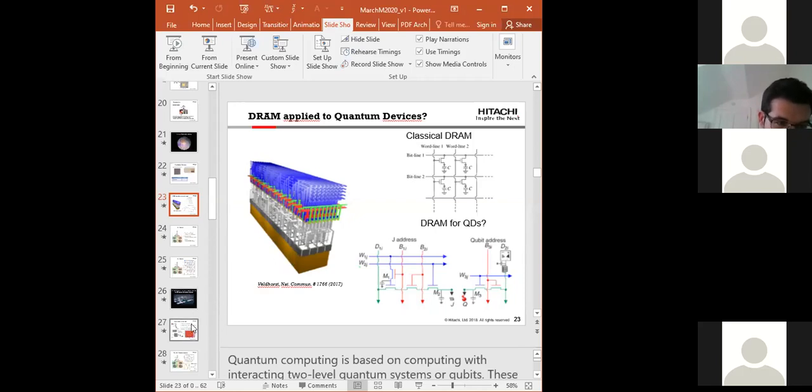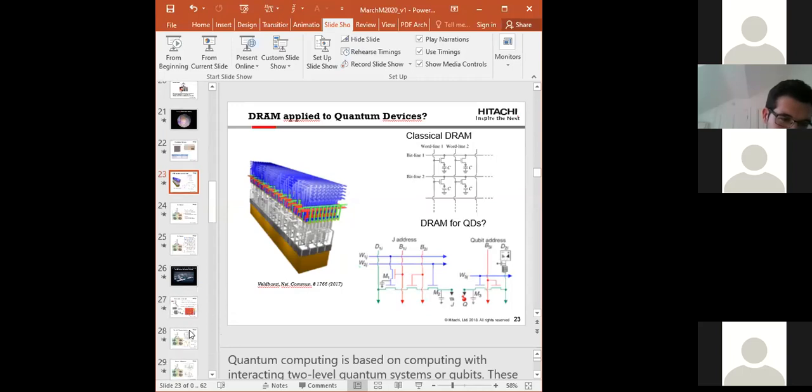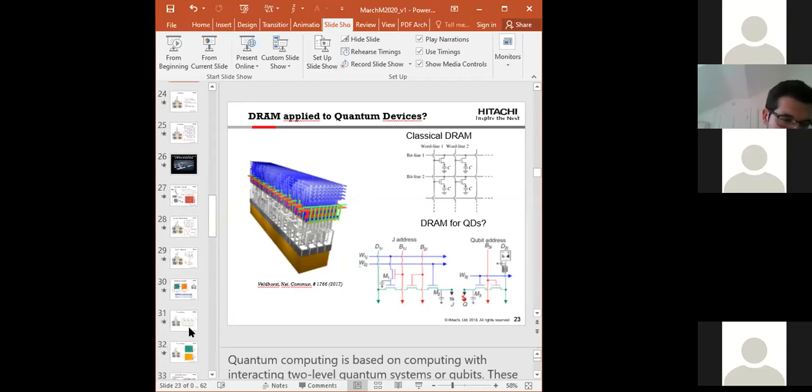Yeah, I know what you mean. So we talk about the resonator. Yeah. Now we talk about the storage capacitor. In this description, yeah. Unfortunately, the footprint of the storage capacitor was not properly accounted for. They were talking about a 1 picofarad capacitor that was necessary there. That's huge. That has a very large area. But nevertheless, it was a very good proposal.